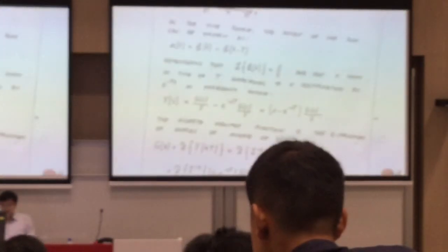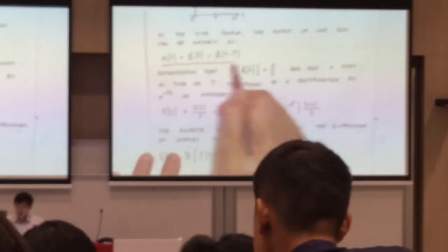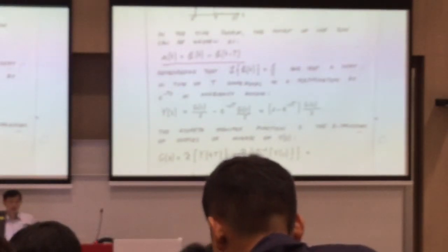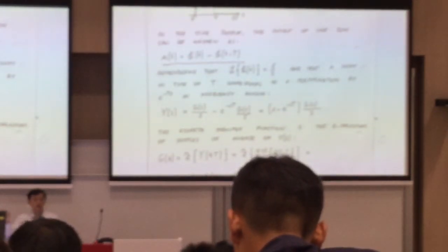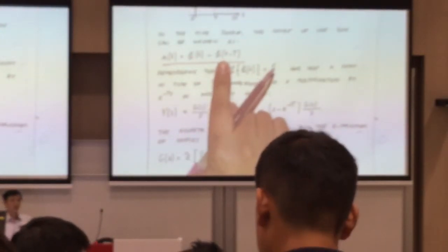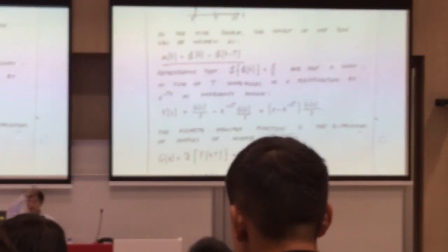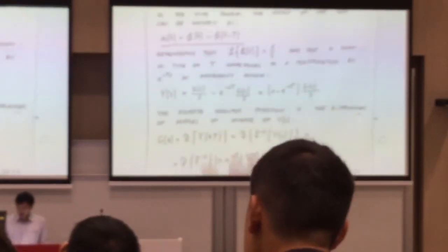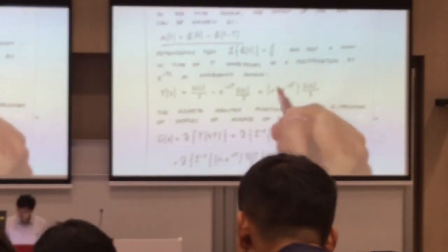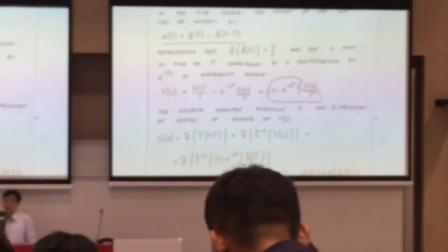So for the zero order hold, basically you hold, so this is your time equation for the zero order hold. You hold for one period. So this is 1 minus the signal delayed by one period, because you only hold for one period. And you do the Laplace transform of this one, and you will get this as the Laplace transform.